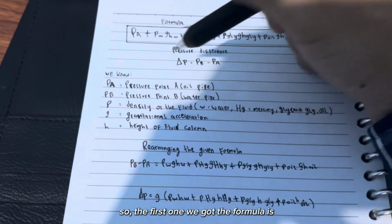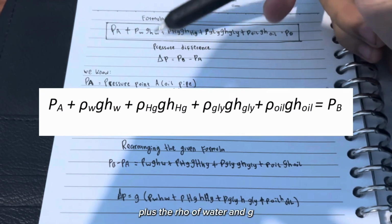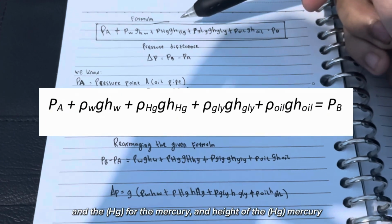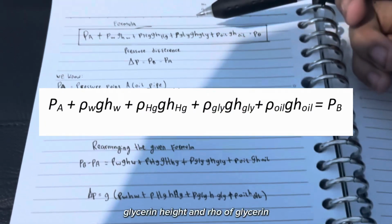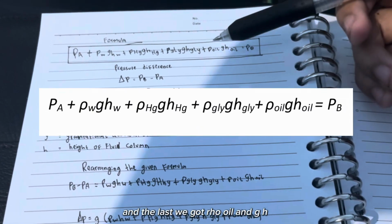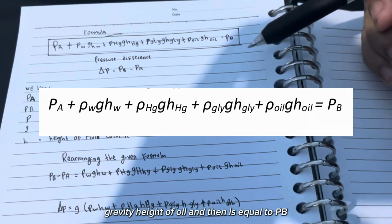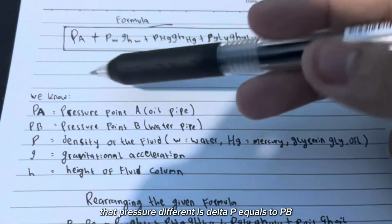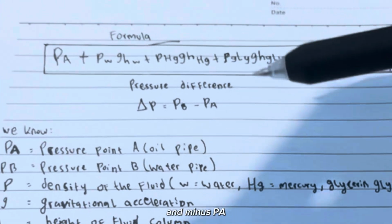For the first one, we get the formula: PA plus rho of water, g, h of water, and rho of mercury, g, height of the mercury. And next we got glycerin height and rho of glycerin, and the last we got rho of oil, g gravity, height of oil, and that is equal to PB. And as we know, pressure difference is delta P equals PB minus PA.